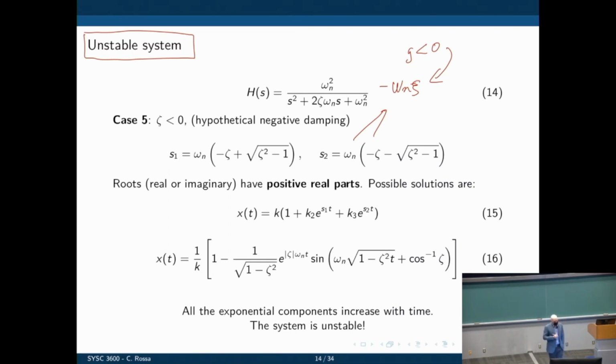If the real part is positive, we don't even need to bother about the other parts of the system. Because what happens when the real part is positive? Remember from the first order system? Now exponentials grow to infinity. And if exponentials grow to infinity, it doesn't matter if it is an exponential or an exponential plus a sinusoidal, everything blows to infinity. Right?